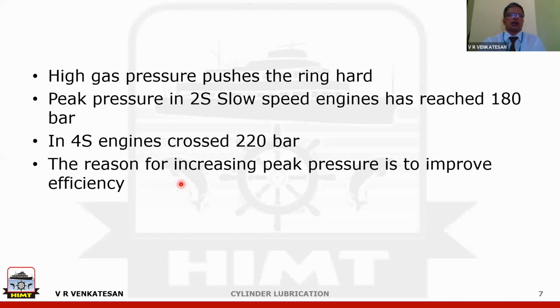For this, the combustion has to be very rapid, and whenever you have rapid combustion, you will get high peak pressure. So there is a connection between peak pressure and efficiency. And if efficiency is high, it means your SFOC will be less. So that is the reason engine makers are constantly trying to increase peak pressure.